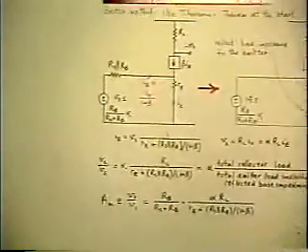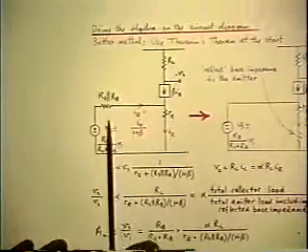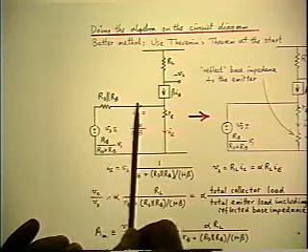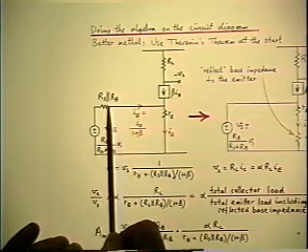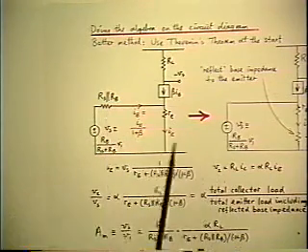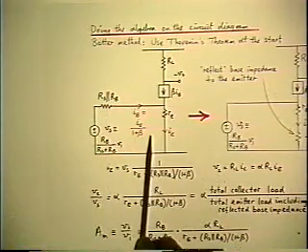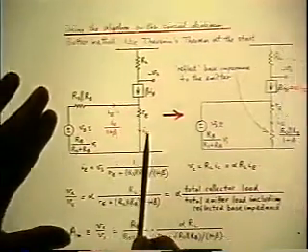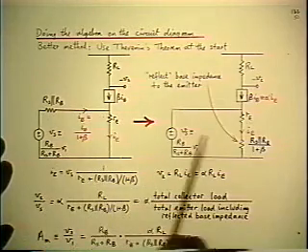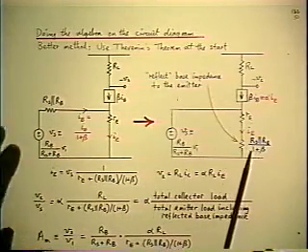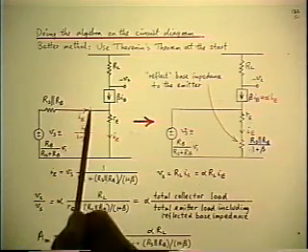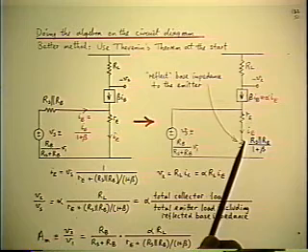Which immediately gives you this picture. Here's the Thevenin equivalent source, which contains the divider ratio. Here's the Thevenin equivalent impedance, gives you RS parallel RB. Now, we can do this reflection process backwards. We can reflect the base impedance into the emitter by dividing its value by 1 plus beta. It's using the same property, the fixed ratio between the base and the emitter currents.